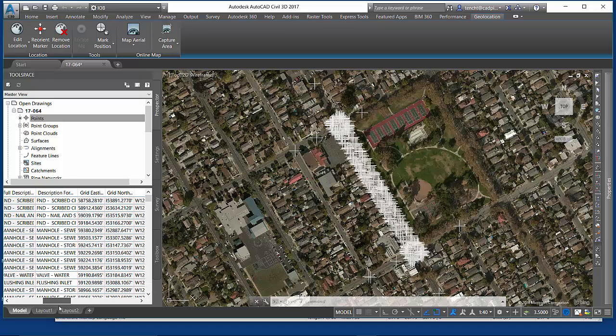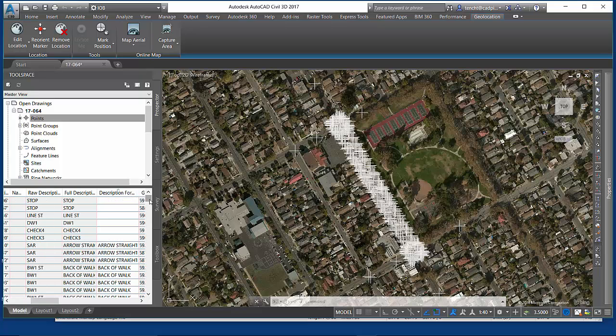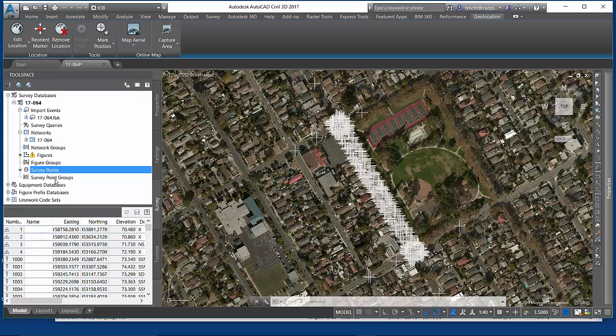But the real issue is I use in my check, in my description format column, if it's blank, those did not match. So I only got 4 or 5 points here. Got to go back and adjust the descriptions to match. Those are the first things I want to get straightened out. You'll notice the descriptions will still come across, but those ones did not match anything in my typical description key set, which probably may not mean this DW1 may not match a figure, so it may cause me a problem, and I want to get those sorted out. I really don't need the points in my drawing.